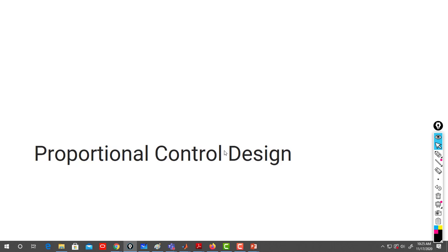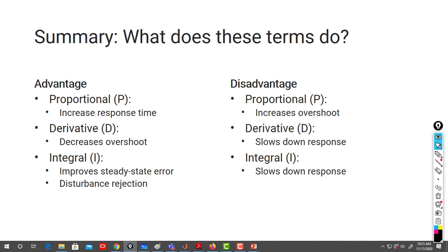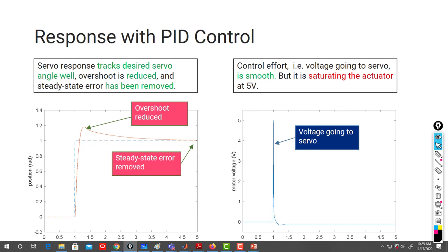Doctor, how do we not saturate the actuator? But it's a trade-off. If you don't want to saturate the actuator and you need to track well, maybe you need to slow the system a bit. Then you tune your parameters. In the case you slow the system, you don't go as fast as this. Maybe you allow some more overshoot in your system. The more you want perfect tracking, the more voltage, more control effort you need to provide to your actuator to react faster.